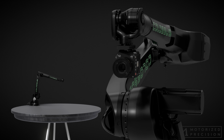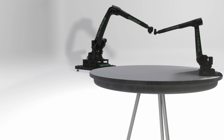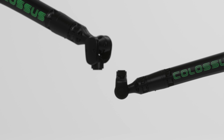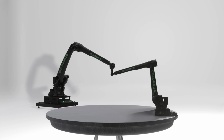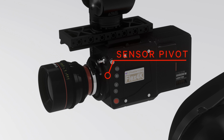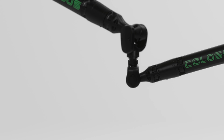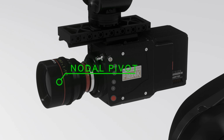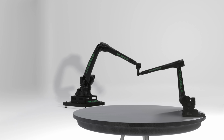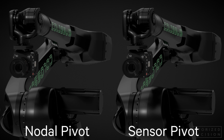But if we pan or tilt, this configuration produces a parallax effect. In most cases, this is not a problem, and it's a fair trade for the extra agility we get. However, if we wanted to do a panorama, then this parallax would be an issue. To achieve a panorama with no parallax, we would need to pivot around the camera's nodal point. Now we can see that the parallax is gone when we pan. Notice though how the camera and the robot have to move a lot more in this configuration.